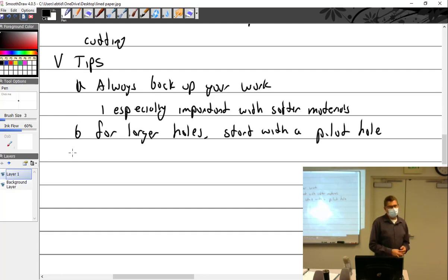And, you know, I started drilling holes more in steel. I learned most of my stuff in cars and then on ships. Ships are not known for being aluminum and very lightweight. So I'm drilling a big, thick plate steel and stuff. And to do that, if I was going to drill, say, a 1/2-inch hole, where was that drill bit that you guys are looking at? It's about 1/2 inch, I think. Is it 1/2 inch? Yep. Yeah, it's about half. So I'm not going to drill a 1/2-inch hole. I'm going to start with an 1/8 inch and drill what I call a pilot hole.